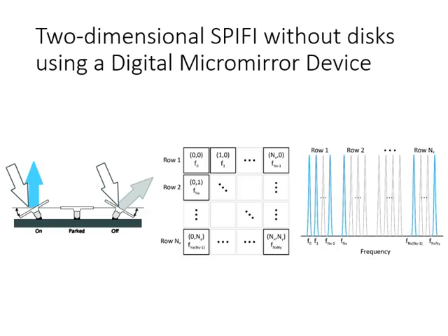So then we said, what happens if we avoid spinning disks altogether and go directly to DMD? A DMD is just a large array of mirrors which can be switched on or off quite rapidly. Each of these mirrors in the DMD array is being blinked on and off at a different frequency. And so the spatial information from a certain point is written directly into the amplitude of a different frequency in the electronic spectrum. However many frequencies you can capture and however many pixels you have limits your image formation.